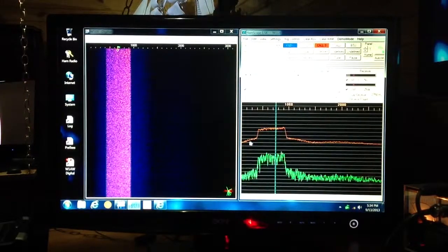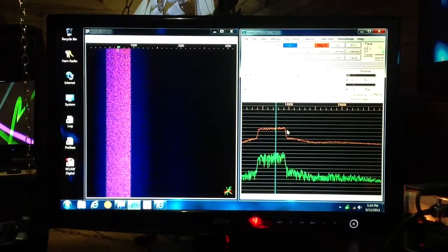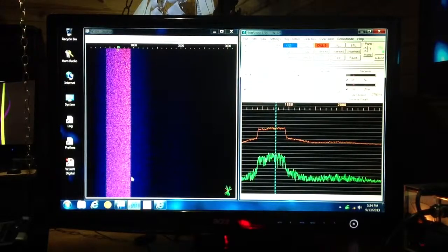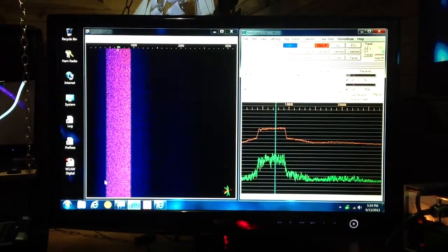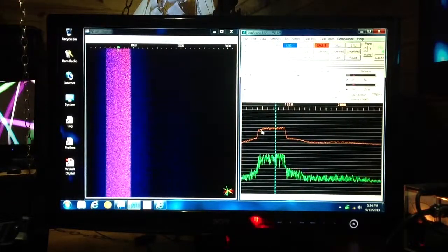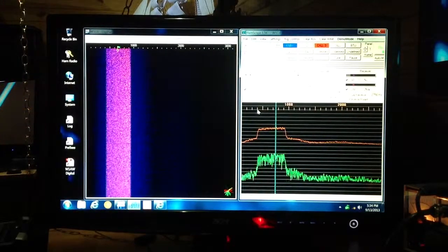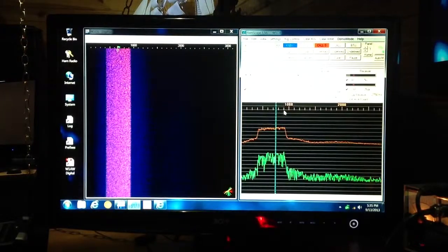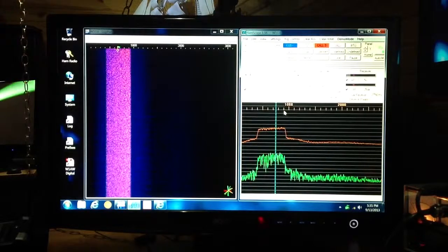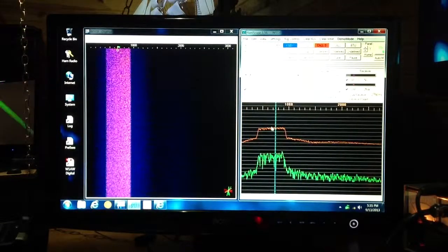By rectangular we mean that the skirts, that's these edges right here and right here, and also on this program right here and right here, are very steep and sharp, so that the range of frequencies that it will let through, in this case roughly 400 hertz to 900 hertz in the audio spectrum, is 500 hertz wide, centered right about at 650 hertz.